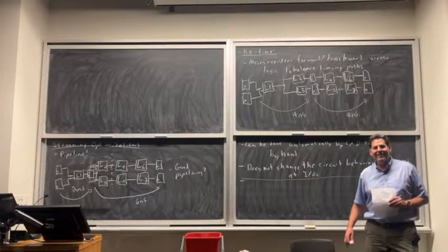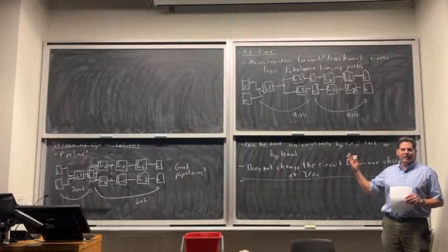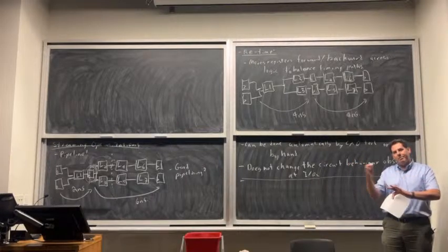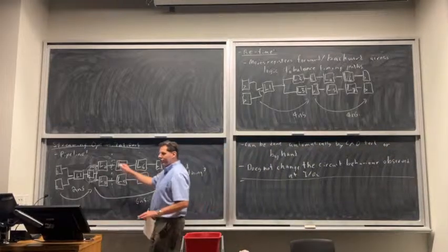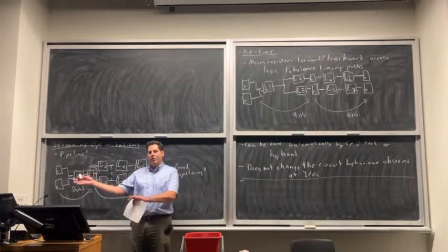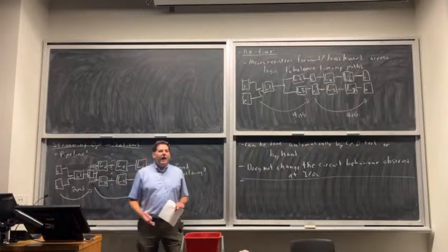Not sure? Okay. So it's still useful to be able to retime by hand at the RTL level because you tend to do bigger scale retiming. You don't even know exactly where the LUTs are. You just look at the timing report and you see this path is long, this path is short. I'll try, could I move this register to a different spot in my RTL?